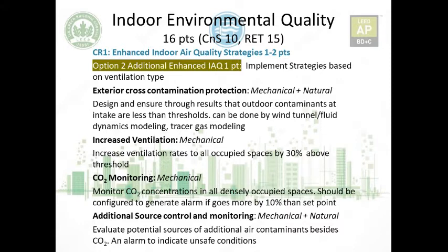The second is mechanical, for mechanical ventilation system, providing increased ventilation above 30% than the required threshold. The more ventilation, the better, in the sense that the air is changed. So if you put 30% more, you're making sure that the air is not polluted, or there are no contaminants